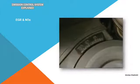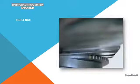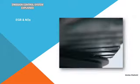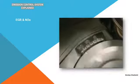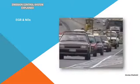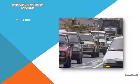Oxides of nitrogen can also be reduced by retarding ignition timing. This lowers the maximum temperature reached during combustion. The maximum ignition advance setting is then said to be emission limited. However, it also lowers engine output and increases fuel consumption.